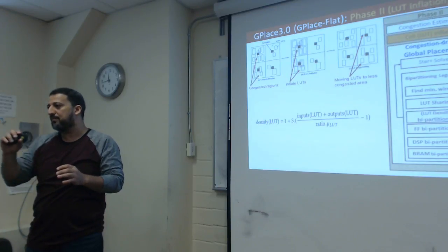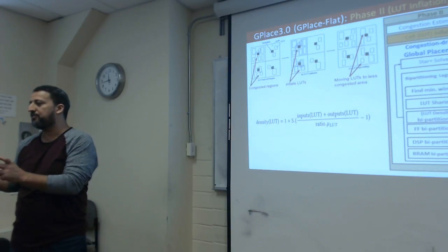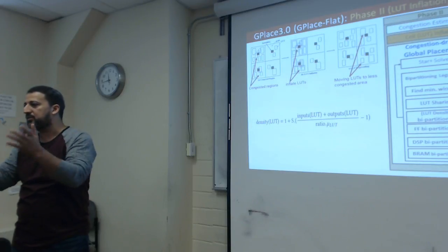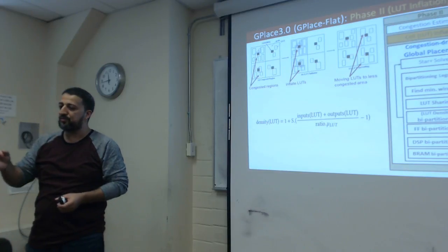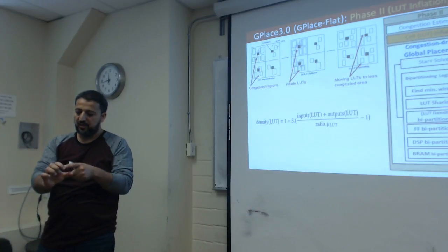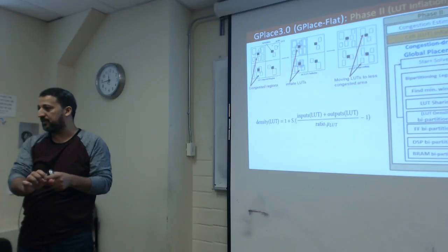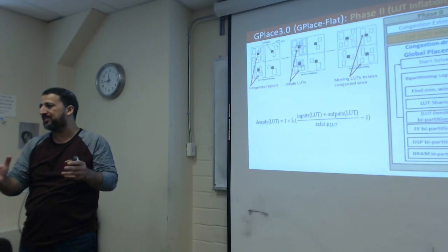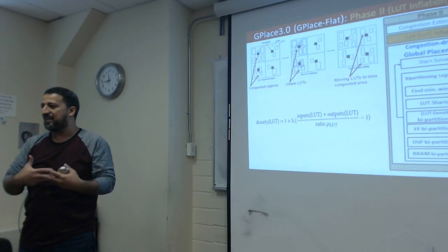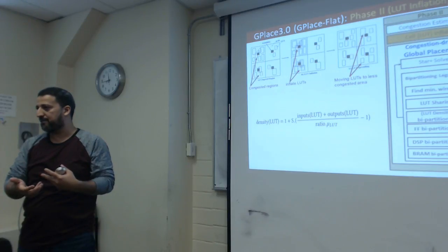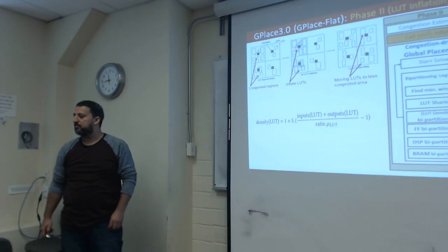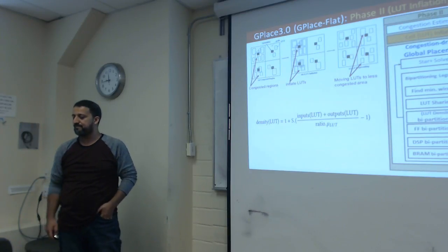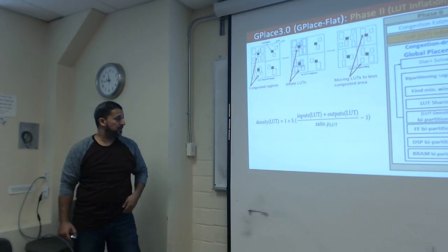Yeah, but also it has some portion of the total congestion, I mean the congestion in total also. Because sometimes you have a congestion value similar for a different placement, but maybe those two benchmarks are not having the same difficulty for routing. Sure. So my interpretation of this is the S is your congestion map. Yes. Correct. It's how congested you are relative to the global congestion, and your inputs LUTs plus outputs LUTs divided by ratio of U LUT.